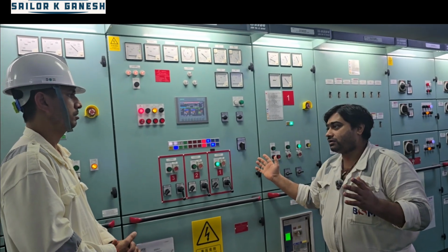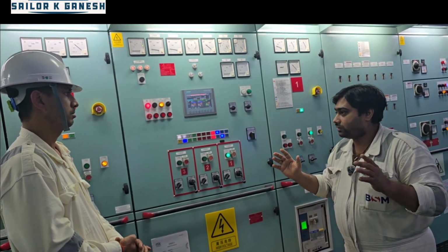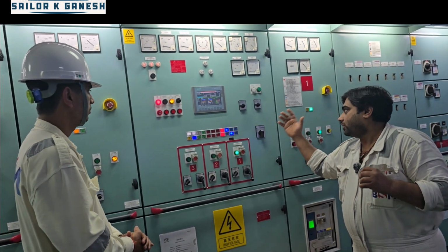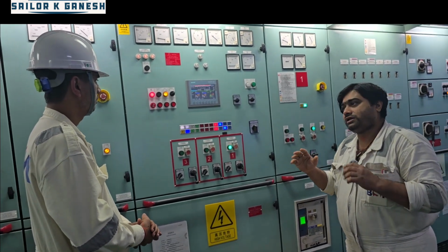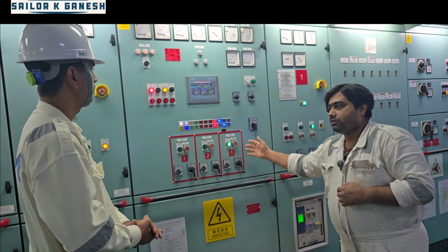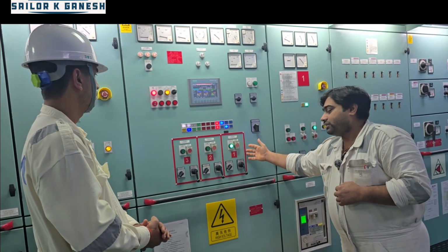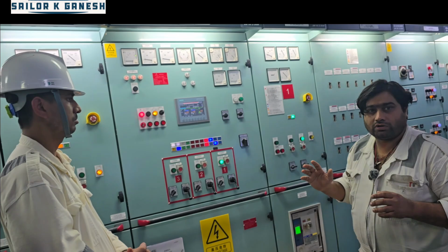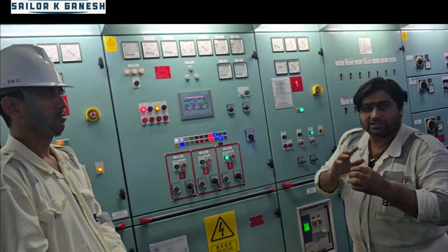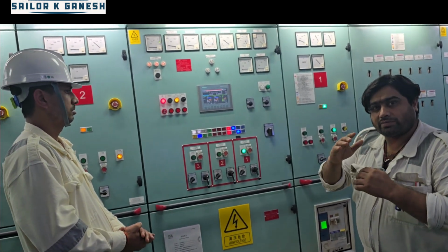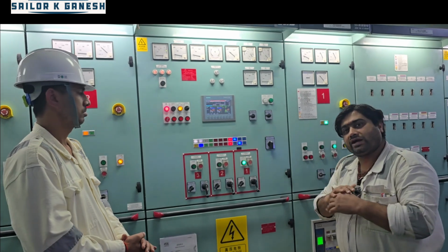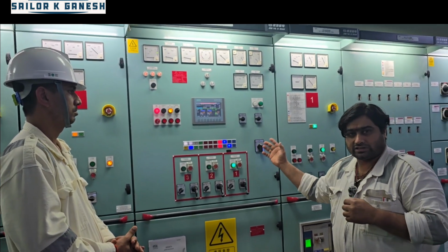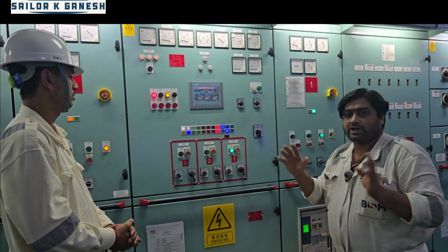At anchor, usually the load is less, so the power distribution while running the ship at anchor is less. So 1 generator will do when the ship is at anchorage. When the ship is sailing, the normal sea load is around 450 to 500 kilowatt, with some extra power whenever other machinery cuts in. At that time 1 generator is sufficient for normal running of the ship.